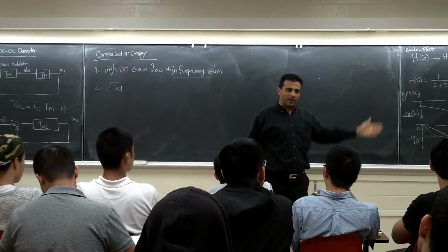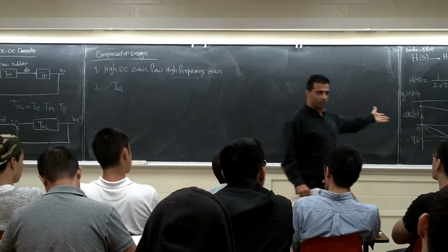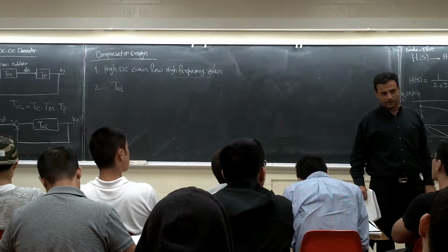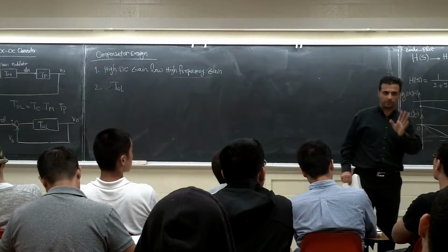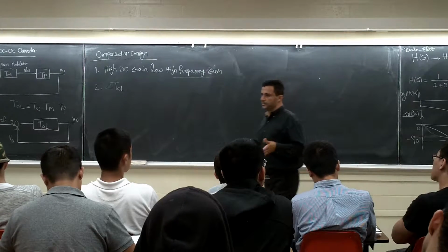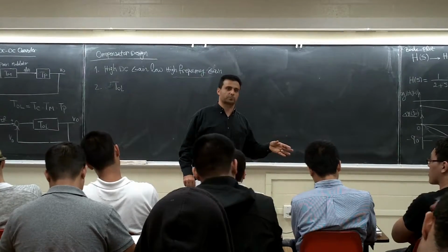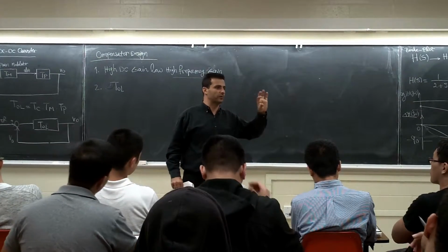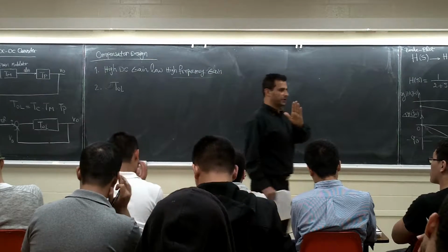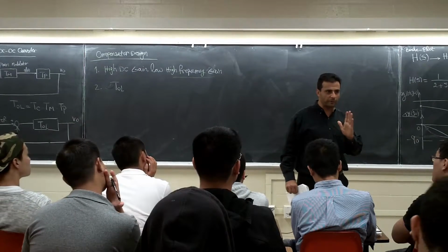If the switching frequency is 10 kilohertz, we go with 1/10 of it, 1 kilohertz, right? We don't want to see anything more than 1 kilohertz in the waveform. You want to get rid of the effect of switching frequency in your measurements and everything. When you design a filter, lots of times when you sense the current and voltage in the power converter, you need to design a simple filter to clean up the waveform. Usually, the corner frequency of that filter, you can select 1/10 of the switching frequency, 1/5 or 1/20.